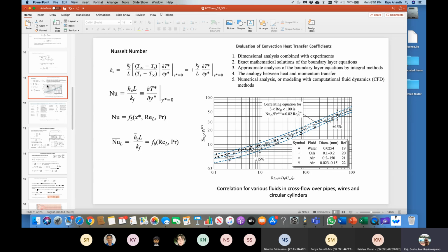All right, so now I want to define, so the whole idea is from the Nusselt number, which is hD over k. So if I want to get the Nusselt number, the fluid conductivity divided by L, everything is dT/dy as y goes to 0. That is how I'm going to calculate. k dT/dy is my conductive heat transfer.